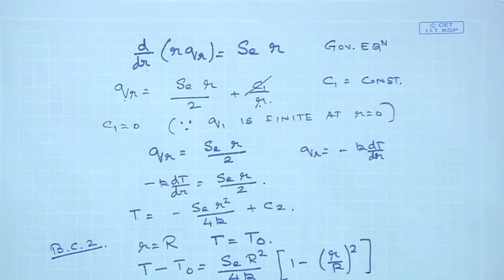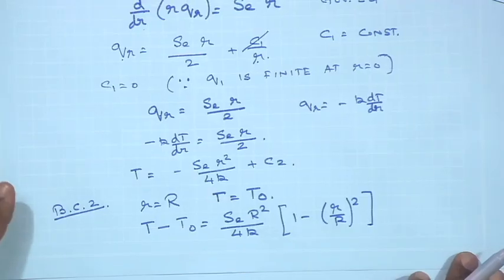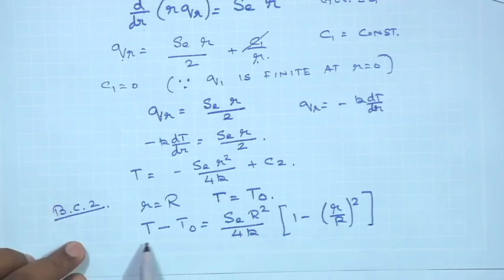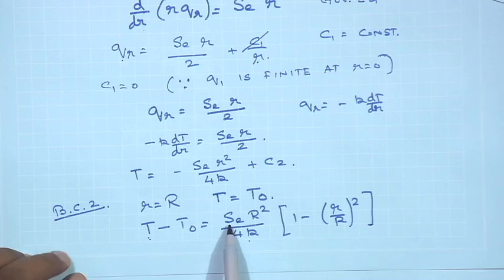So, what you see here, I would point to this equation once again. The temperature distribution, which is a function of r, with T0 the temperature at the outside of the wire, is a parabolic function of r containing terms such as the thermal conductivity of the solid wire and the heat generation per unit volume due to the passage of current through it.